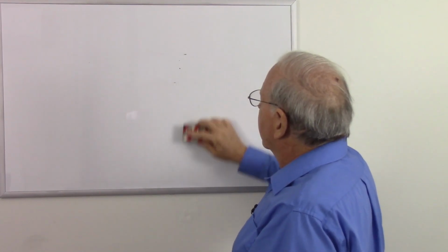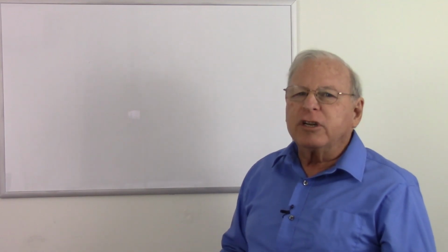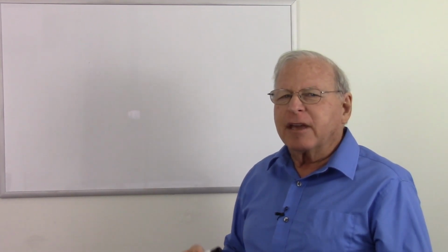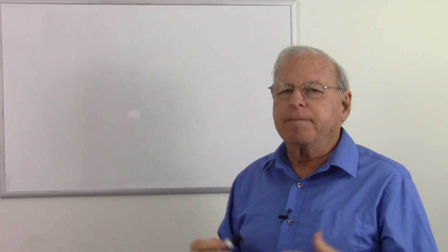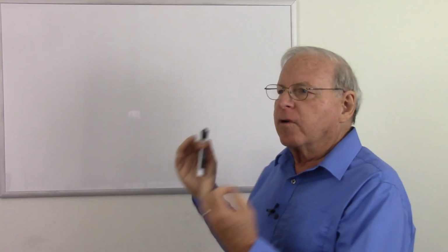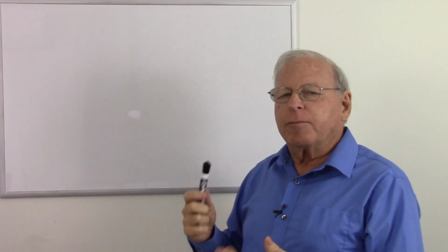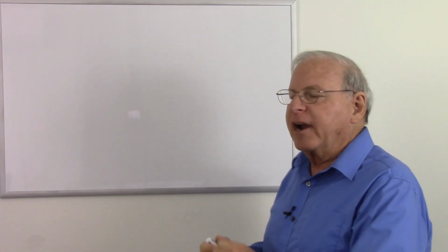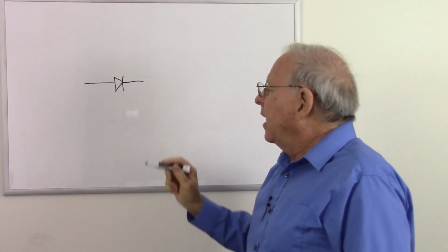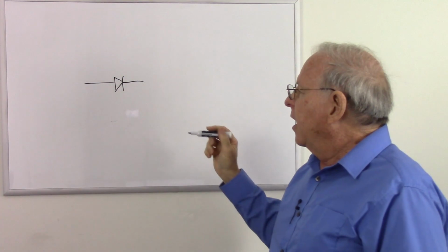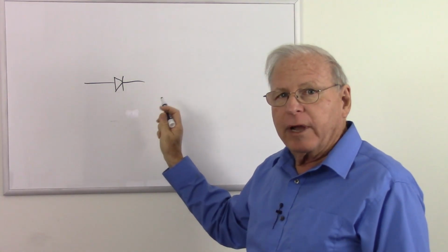Now what we're going to talk about are small signal diodes, switching diodes, and rectifier diodes, because those are your basic diodes that we look at this particular principle at how they operate, normal operation where we work them forward biased to conduct, reverse biased to non-conduct. So let's talk about those small signal diodes, switching diodes, and rectifier diodes. The symbol is the typical diode symbol, and they're used for small currents and just as basically electric check valves to allow current to flow one way but not the other way.